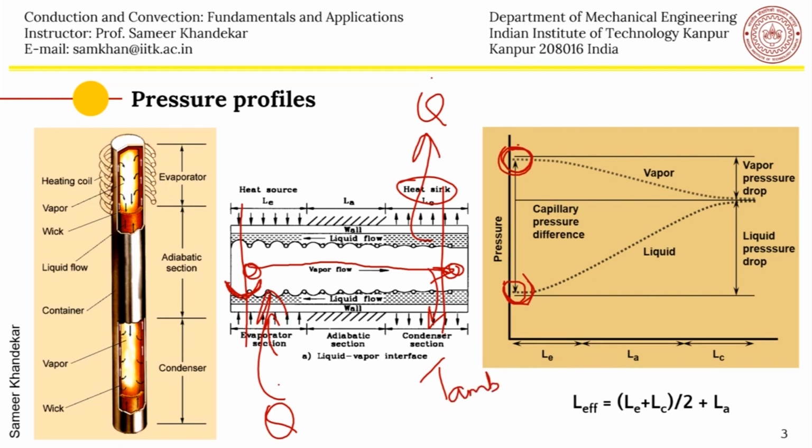The vapor will condense, and since flooding conditions are here, the radii of curvature will be very large, in fact, and the vapor pressure and the liquid pressure will tend to be equal here. If they are absolutely equal, then this meniscus curvature will be flat.